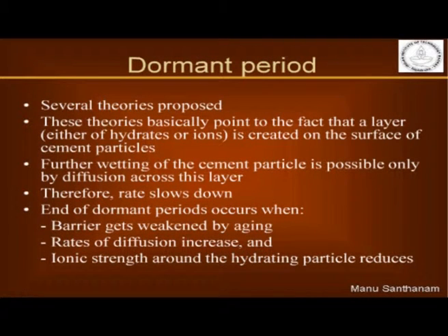So again, why does this dormant period occur and what is its significance? Please remember one thing: when you're mixing cement and sand and stone and water together to make your concrete, you need a certain minimum amount of time during which you are actually working with the concrete, because you need to mix the concrete, convey it to the job site, deliver it into the formwork, then compact it, then finish it. So many different operations have to happen without the cement actually setting.